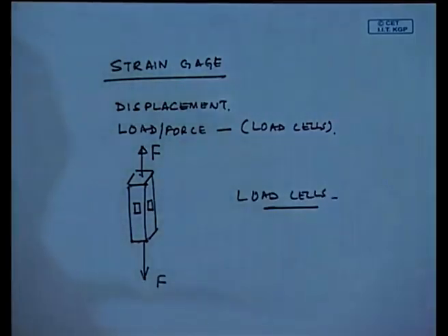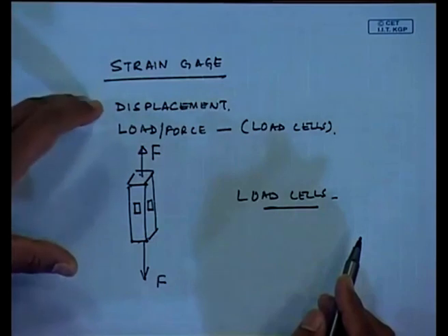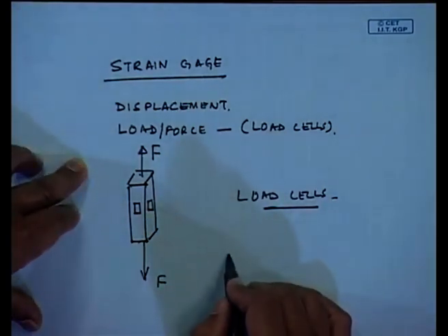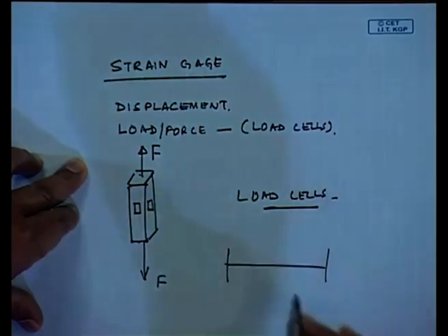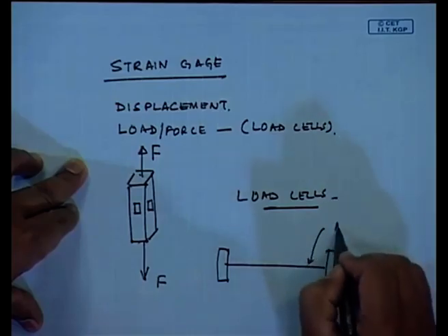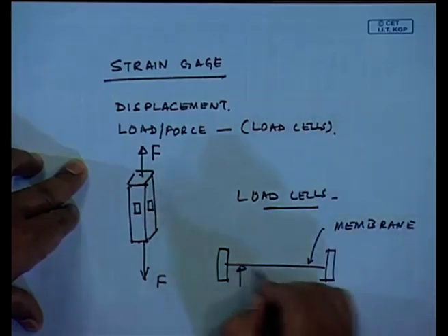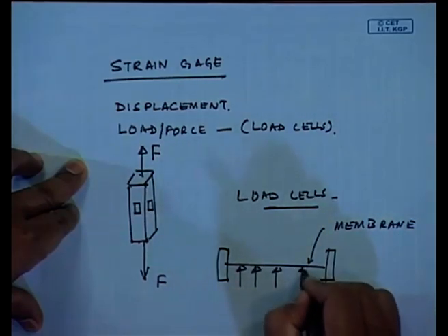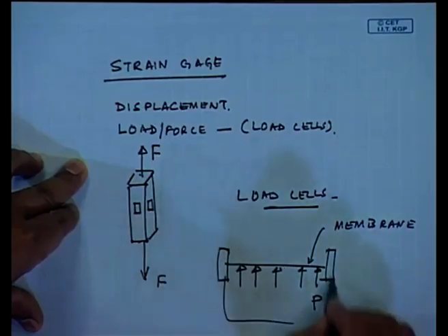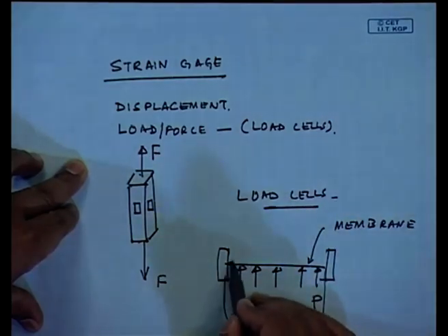So, an electrical resistance strain gauge is this sensing element, but the mechanical parameter could be load, could be displacement, could be pressure. For example, there are diaphragm types of pressure gauges, okay, and these are held in this thin membrane. And there is a certain pressure P here, and of course this is in a housing, etc.